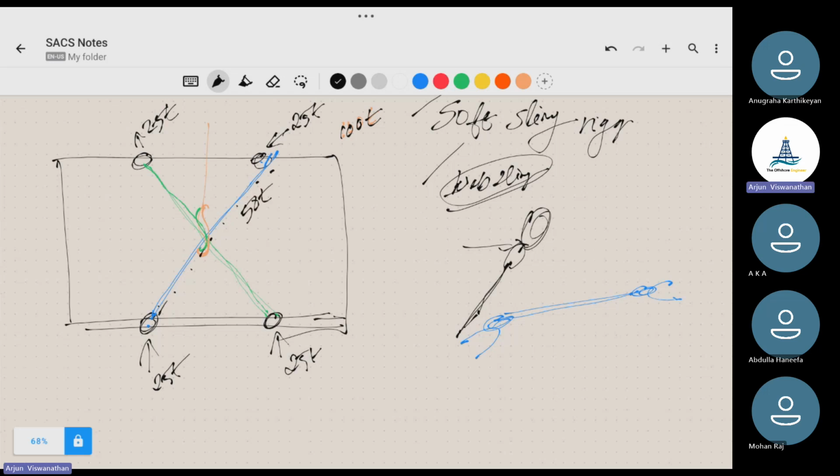The incline tension will be varying, that's okay, but totally it should take 50 tons. This one will also take 50 tons. Now, our assumption was equal length, everything. Just consider that due to some fabrication tolerance issue, one of our slings becomes slightly lengthy. It won't be that much, only slightly. When you connect, you don't feel the difference overall, but it's slightly lengthy.